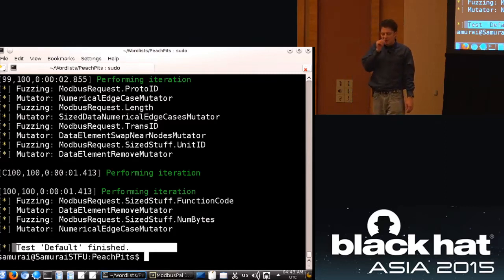So the scanning tools that will go through and do it, most of the policies, if you look at something like Nmap, there's a Modbus NSE script for Nmap, and all it does is enumeration. If it finds something on port 502, it tries to pull down identifiable information for unit ID 1, maybe more, depending on whether you tweak that NSE script. Nessus and Qualys have some audit capabilities for some ICS protocols that are out there. If it's Modbus specific, it's probably enumeration-type information.